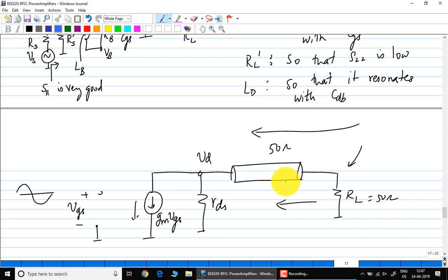Okay, a lot of wireless LAN chips today do have integrated CMOS PAs because the wireless LAN spec puts out about a few hundred milliwatts of power. So it is just barely possible using CMOS. Okay, Bluetooth definitely, you don't need an external PA at all. Low range, short range devices.